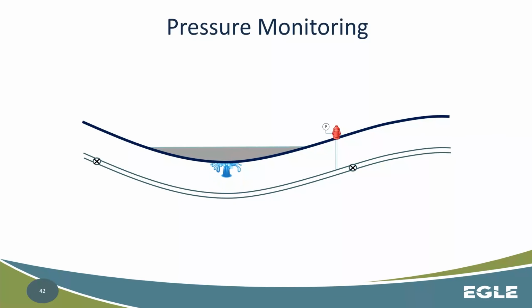So another issue here is when you have water crossings, or, I don't want to call it a crossing. I guess you're crossing it, but you're really going under, right? So let's say you've directionally drilled under a lake or a river or a pond or some sort of body of water. If you don't have some proper gauging before and after, or between those points of low end, you could get a break or a leak that occurs under that water body and you would never know it.